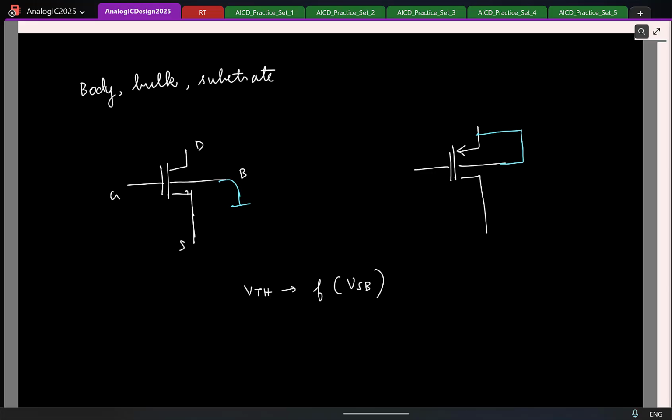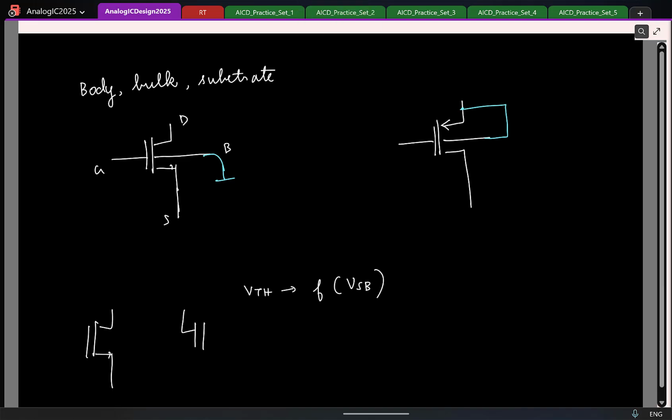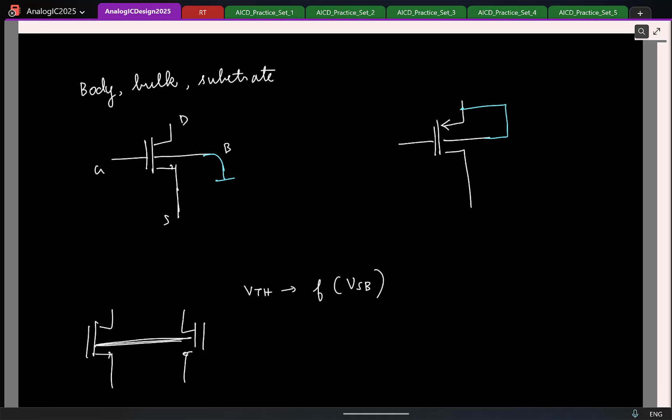No, it is not about the VTH. Like I told, all the NMOS transistors, as you might learn in the solid state devices course, by construction share the same body terminal. So this is basically connected, but the point is, this is connected to the lowest terminal. Yes, definitely, correct. It will be different for both. Whether it's a feature or a bug, it depends on you.